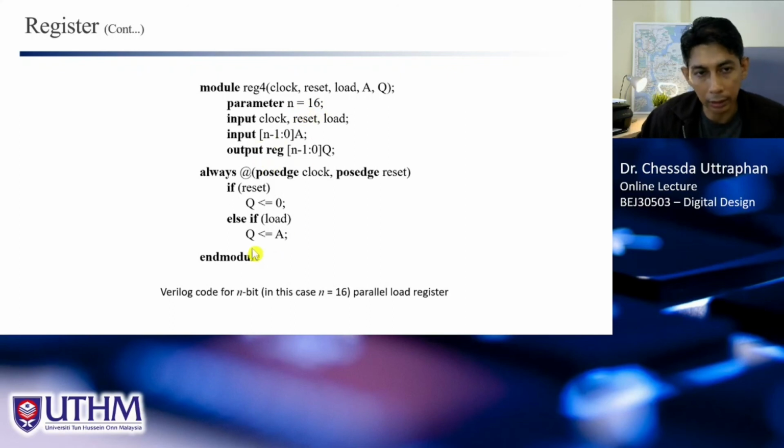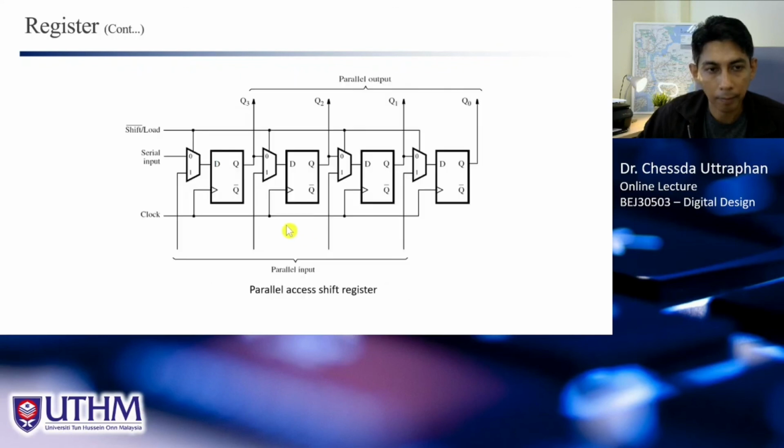This is a very useful technique in designing a digital system, where sometimes we want to upgrade our design from a smaller design, 4-bit, to 8-bit, or 8-bit to 16-bit, or even bigger. So by using the parameter like this, we can change the size anytime as we want.